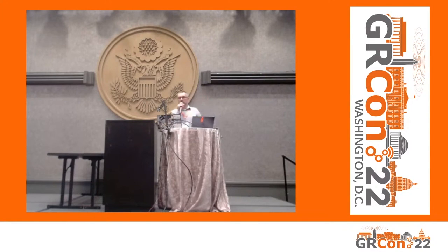I think the other gentleman just mentioned that. Obviously C++ or C will let you do that as well. The GNU Radio block, I think you can send messages to it to toggle that, so it's using the message passing interface. I don't know the exact API, but I think that's probably in the manual actually. I know not everything is documented, but I'm pretty sure that is. So you send a message command, and you can include a timestamp, so you can do timed toggles that way as well. And there is also a Python API exposed through GNU Radio that you can use, and it does the same as the UHD API.